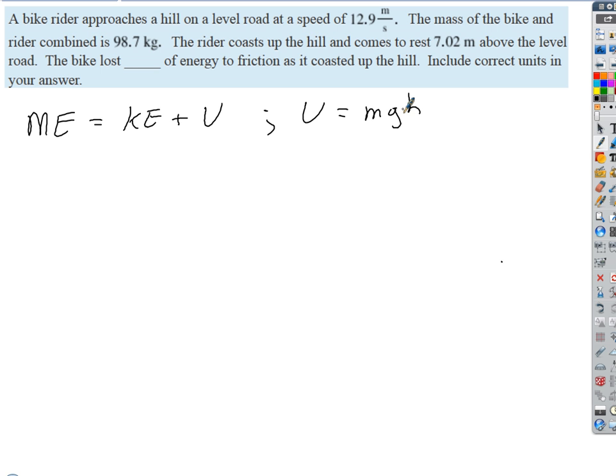It becomes a generator. So you use the kinetic energy of the car to spin the rotor, which resists you, because you're driving magnets against each other, which generates a current, which charges the battery, right? So the braking force is actually an artifact of the process of storing energy.